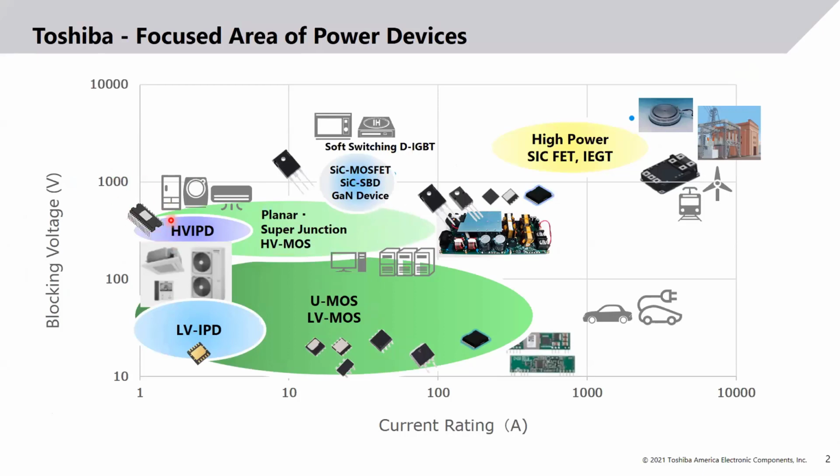Also integrated small power modules for 3-phase motor drives, and modules for very high power industrial applications. We have all industry standard packages, surface mount 5x6, and dual side cooling 5x6, for example, which is being used by Siemens today during the webinar for thermal testing evaluation. Also our super junction DTMOS 6th generation super range high voltage MOSFET as well.